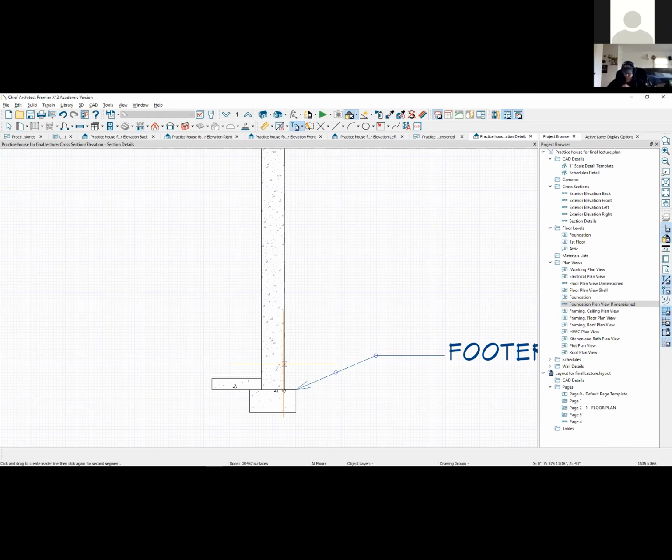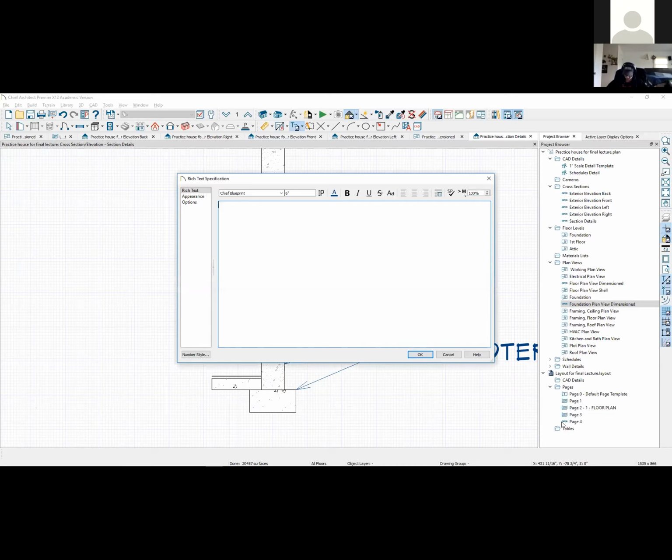And if I use that same angle snap, I can align it with the line below it by just hovering over until I get that snap, and then drawing when I get the little X. So this is going to be my 8". I can't remember it specifically.